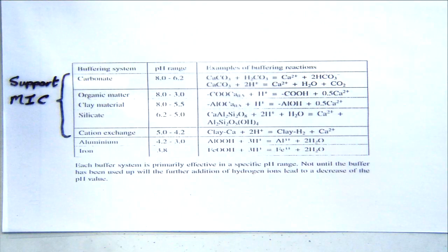I have another question. I found that in marine environments in tropical areas like Southeast Asia, there is accelerated corrosion. Is it because of MIC? Well, it's partially temperature at any rate, because corrosion rate accelerates, as a rough order, about double every 10 degrees centigrade rise in temperature. So it's partially kinetics. But there will also be some bacterial action as well. Temperature accelerates the corroding cathode process.